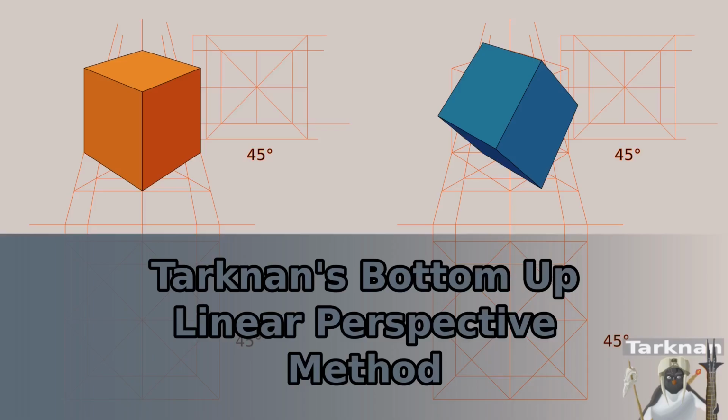Inaccuracy here will result in the incorrect height of cube. Measure at horizontals. Number 3, mark heights of legs and corners. Measure the horizontals where the corners of the rotated cube touch the inner square. These are the heights of the corresponding legs. The heights can be measured, then those measurements can be replicated at 90 degrees to get the height, or a line can be drawn to the length of the reference line and then be rotated and placed. The important part here is that the height lines be taken from the width of the unrotated square.